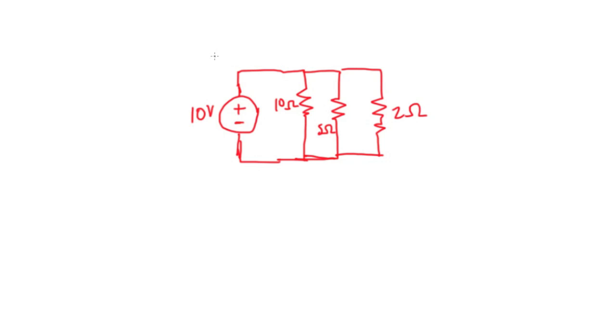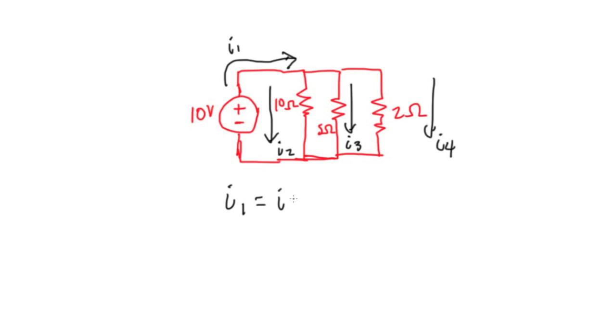All right, so the inherent idea, again, the Kirchhoff current law, let me just use a different color to indicate arrows. I'm going to use black. So the idea is that the current flows in this direction, I can arbitrarily select any direction of current flow. I'm just randomly picking one. I can assign the arrow to be in the other direction, it doesn't matter. But the inherent idea is that I'm going to call this current I1. It's going to equal the sum of the currents that go in here, so one that goes down here, another one that goes down here, and another one goes down here. I'm going to call this one I2, I'm going to call this one I3, and I'm going to call this one I4. So I therefore know that, using the Kirchhoff current law, I1 is equal to the sum of I2, I3 and I4.